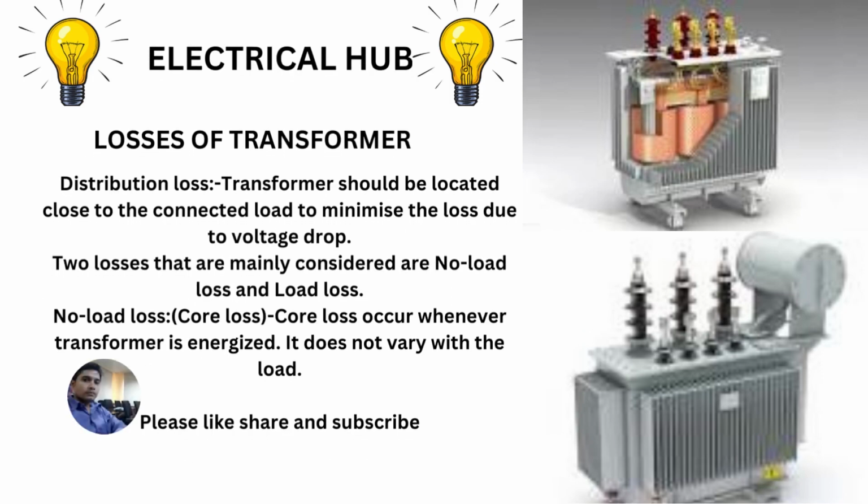Now, let us discuss the losses of the transformer. First, distribution loss. Transformers are basically connected to distribute the power to a section. So, it should be located close to the connected load to minimize the losses due to the voltage drop. Because as the voltage drops, the current will increase and the I square R losses in the line will also increase. There are basically two types of losses in the transformer.